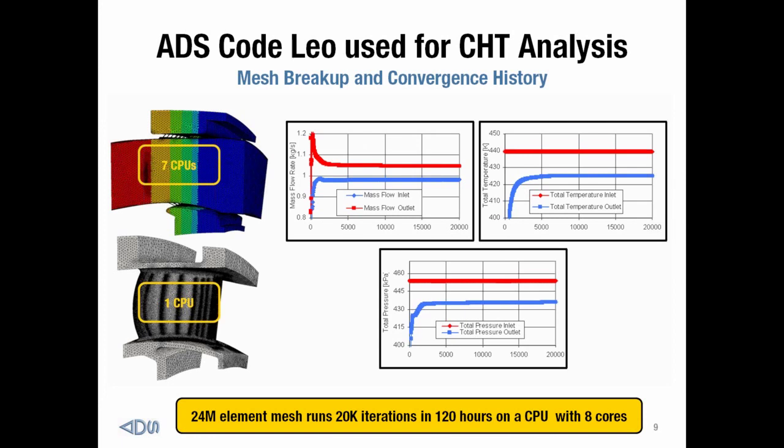If you initialize with a cold fluid, now those coolant cavities start off at roughly the temperature that they're going to end up at, and the core flow region has a relatively high Mach number, so that cold fluid is pushed out of the core flow region relatively quickly. So the lesson to learn here is that initializing to the coolant temperature, so that we focus on the coolant cavities or the low Mach number regions, gives you a much faster convergence rate than the hot type of initialization.